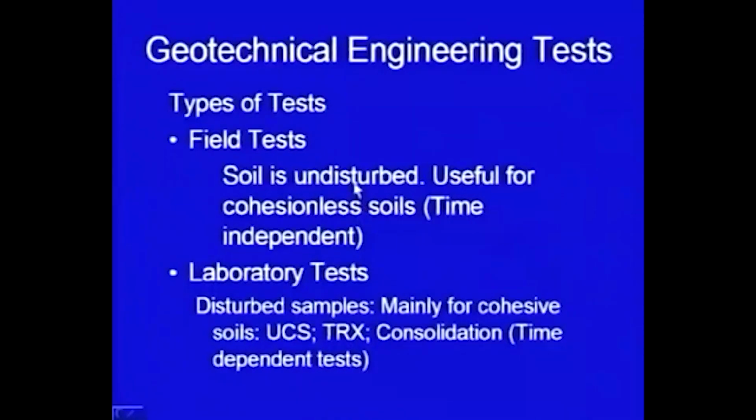The field tests are conducted mainly for cohesionless soils because we have no other alternative. In the field, this soil is undisturbed, but if you try to bring it to the lab, it becomes disturbed. That is why in the field the test is conducted on undisturbed soil and we get representative values. Most of the time these tests are of short duration, time independent tests. Time dependent tests, for example for clays, are conducted in the laboratory.